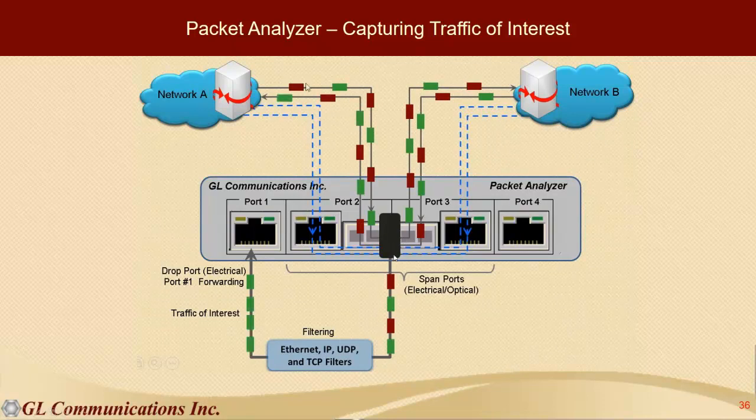When that filter sees something of interest that you have defined, again in the example I mentioned where the PTT bit goes high, we can push those packets on over and then downstream to our timer, our event data logger. And so there's a built-in filtering mechanism here, and that's how we're doing things.